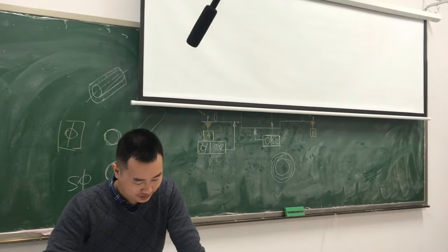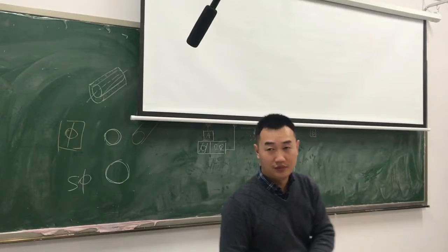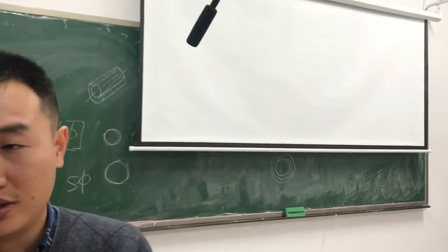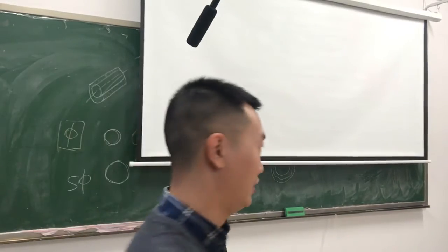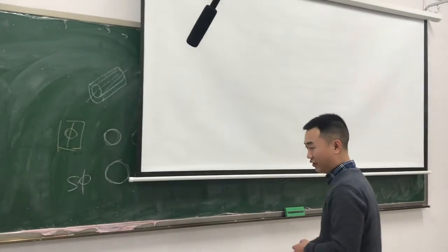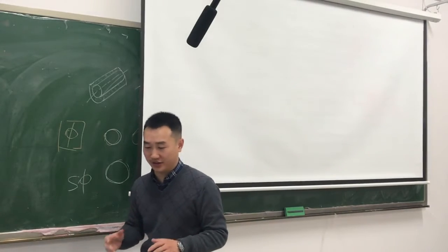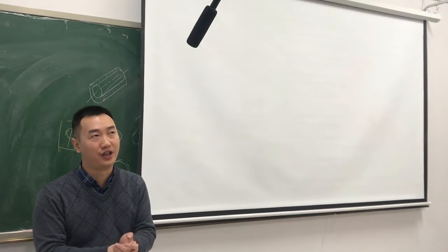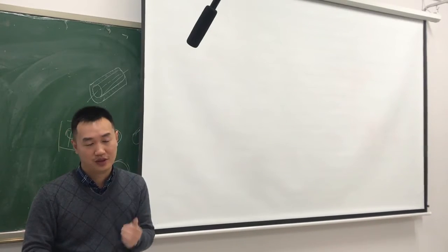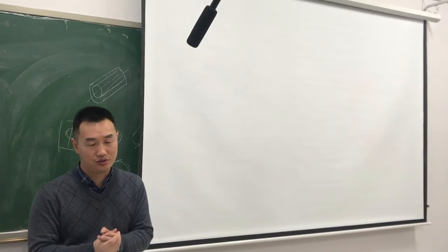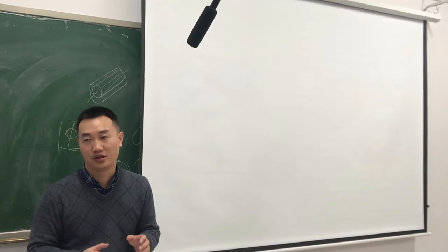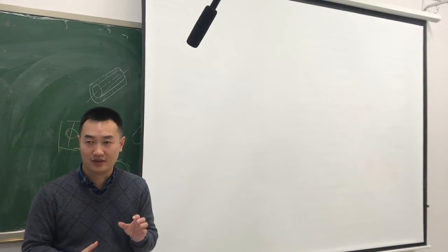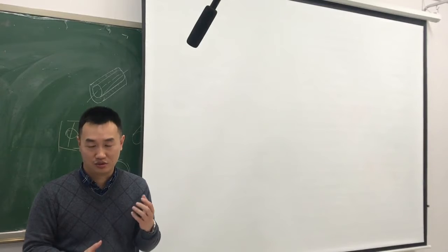About circular runout and circularity, what's the main difference? Because the tolerance zone is the same. The tolerance zones are both the space between two concentric circles, but one needs a datum and the other does not.